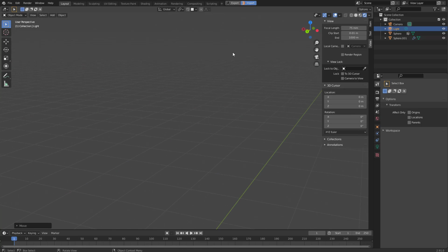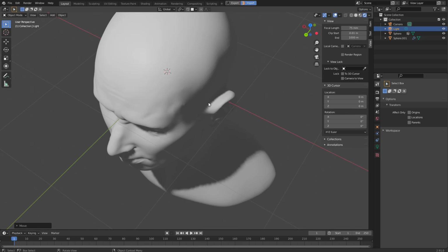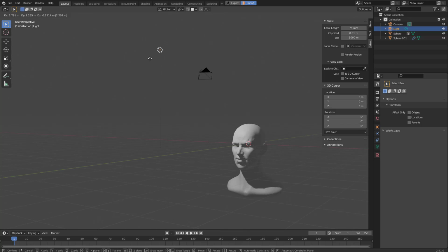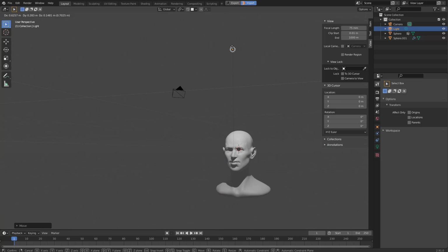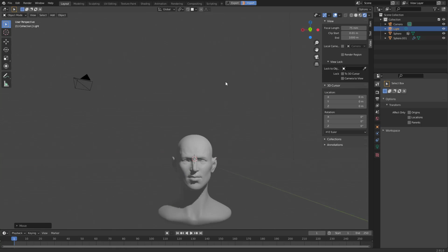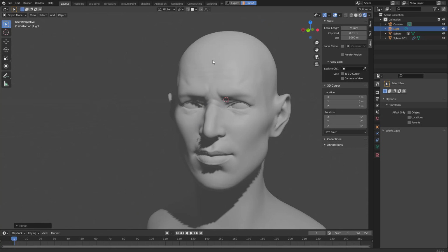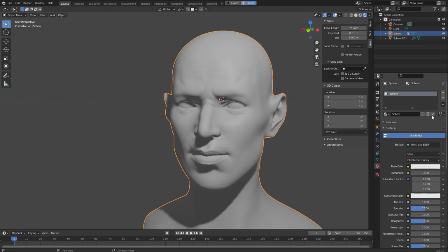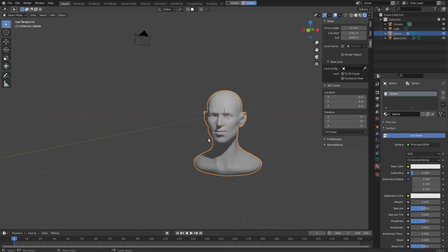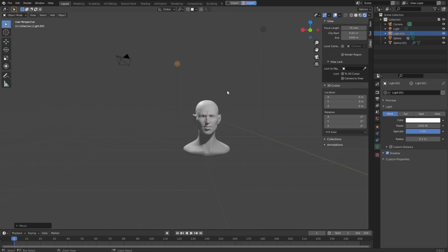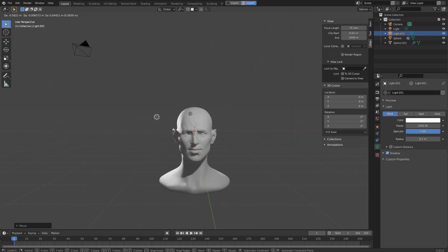And you can see that's where ZBrush needs to learn. Your viewport doesn't render nicely, your lighting system is capable, but really this is way more convenient than ZBrush, like a million times better, right? And the fact that you can preview with shadow and everything, real-time rendering, that's a killer feature. Okay, and then give it a material, maybe have some subsurface scattering, right? Everything can be done there. If I want to have a copy of the light, I can just copy that and drag it over here, and I can easily set up a rim light. I can see it in real time.